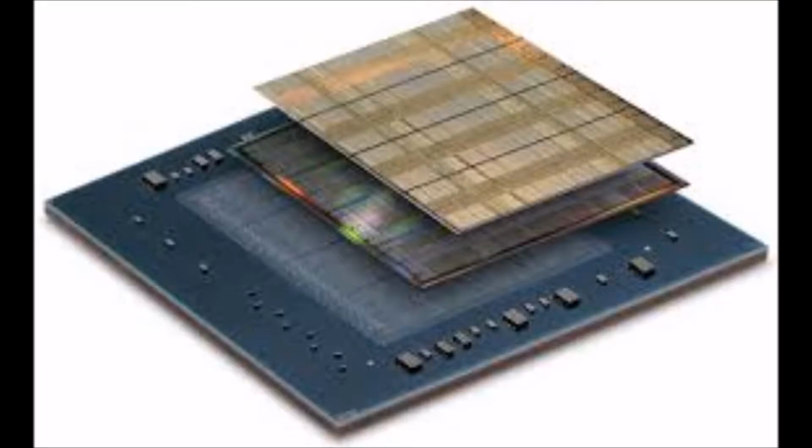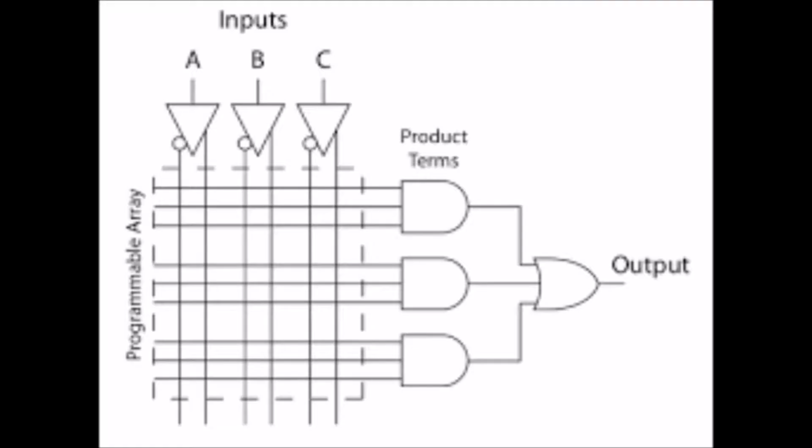The ASICs are devices that may be programmable logic devices, which have gate arrays, standard cells, or full custom devices. The PLDs are the least expensive type of ASIC to develop. As a summary, simple PLDs contain the key element of 600 or fewer gates and are programmed with fuse, PROM, or EEPROM technology, which is in the category that we saw in the chart.